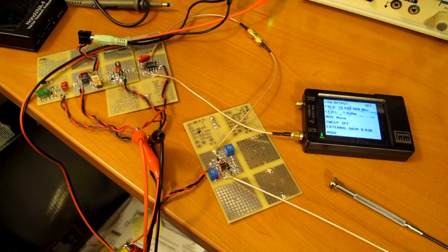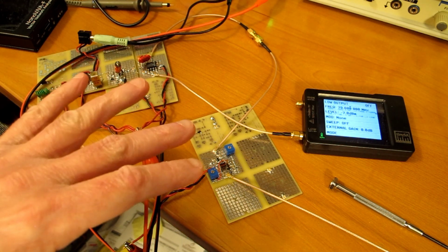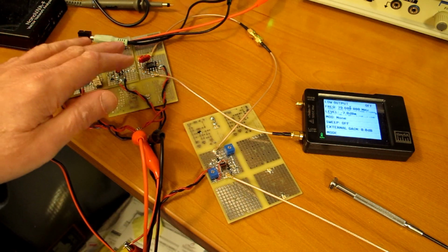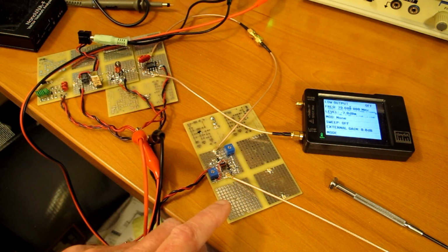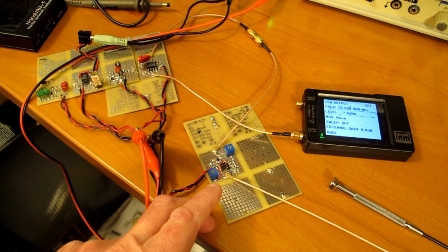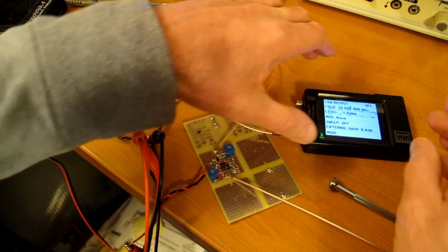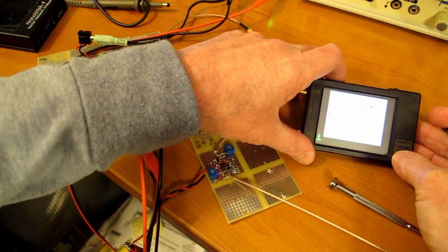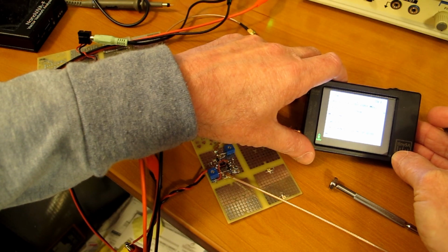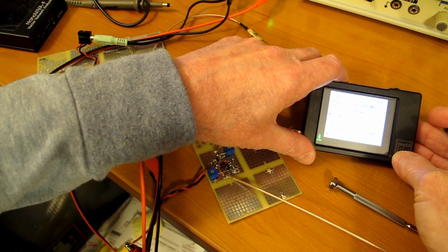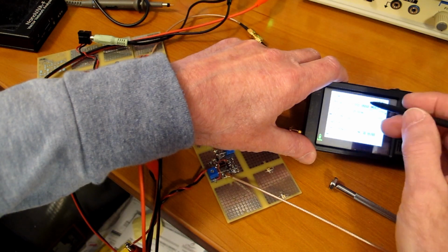Okay, so now let's listen to 90.3 FM on our homebrew receiver from Radio Design 101, augmented with our new Q-enhanced low noise amplifier. I've got the LO tuned to 79.6, which would give us 90.3 if we had 10.7. So let's turn that on and see what we get.